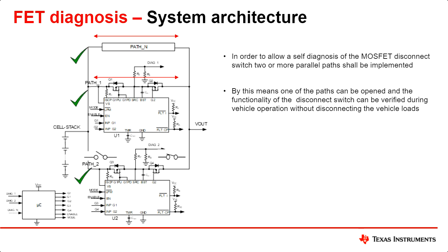Essentially, the middle node of this common source configuration of the MOSFETs can be sensed by the microcontroller, and the gate drive of these FETs can be individually controlled to check whether the FETs are stuck on or stuck off, and the FET diagnosis can be done in this way.